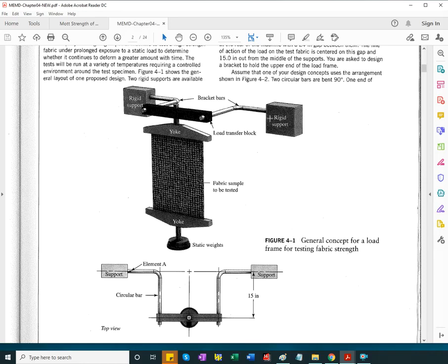But one is axial stress, either tensile or compressive. The other one is tangential stress. And when selecting the material and calculating the design factor, you'd be curious to analyze how this combination of axial stress and torsional stress is going to affect the ability of the material to resist loading.